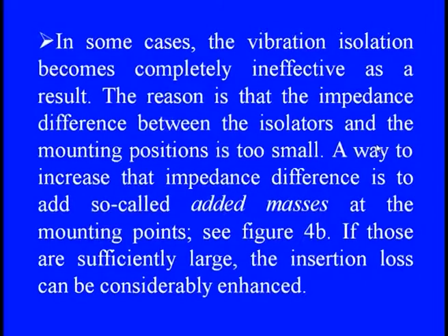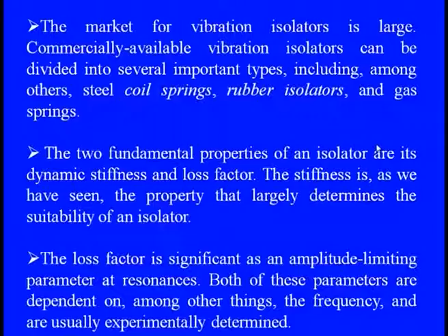And if the mass is large enough according to the system, the insertion loss can straightaway drop down. So, when we go to the market, we know that a variety of isolators are available. We can simply categorize them in various ways, like coil springs, rubber isolators, gas springs.